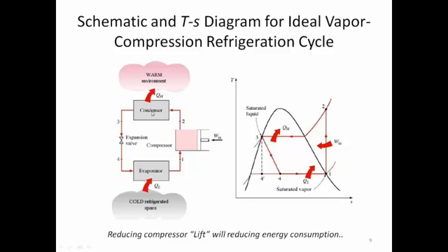So you need to pump it up high enough to get it out to the environment, and of course that's where the environment comes into play with respect to coefficient of performance, because in the summertime it's going to be lower than it is in the wintertime. But all things being equal, the idea behind reducing the lift means that you'll have less work put in, and one way to certainly do that is to bring this temperature on point 1 up. Just drive these numbers up, and that's leaving air temperature, supply air temp, or leaving chilled water temp. If you can get point 1 and 4 really to both move up, then you reduce the amount of area here and therefore the work.